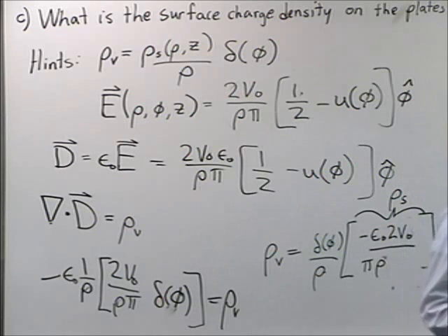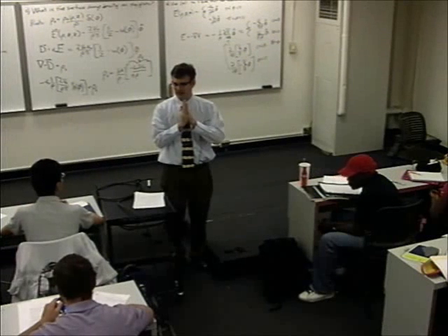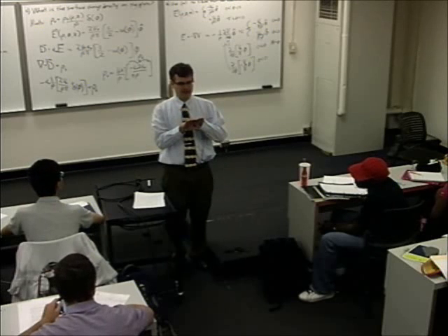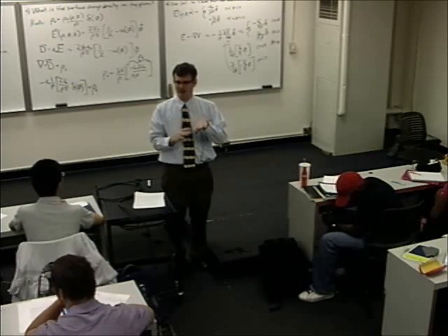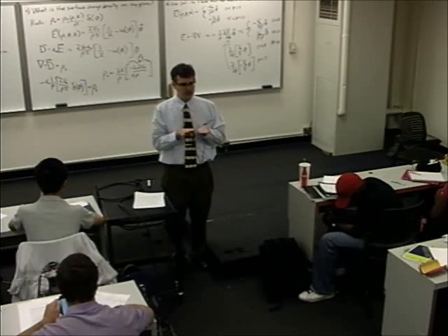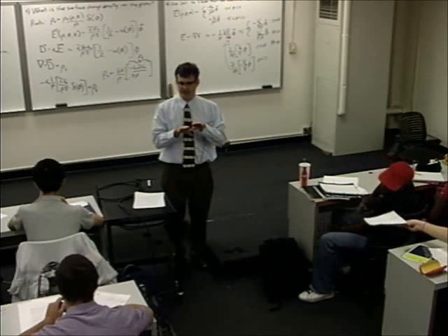So this, in a way, is kind of a very bizarre-looking capacitor, right? Normally, when we think of capacitors, we take the plates and we put them like this. This is the most useful configuration. But sometimes you can have capacitors like this. You wouldn't necessarily want to build a discrete electronic component capacitor like that. It's kind of hard to control the values, and there's an influence of what comes nearby in this configuration on the actual capacitive value. Where might a capacitor of this type of geometry show up?